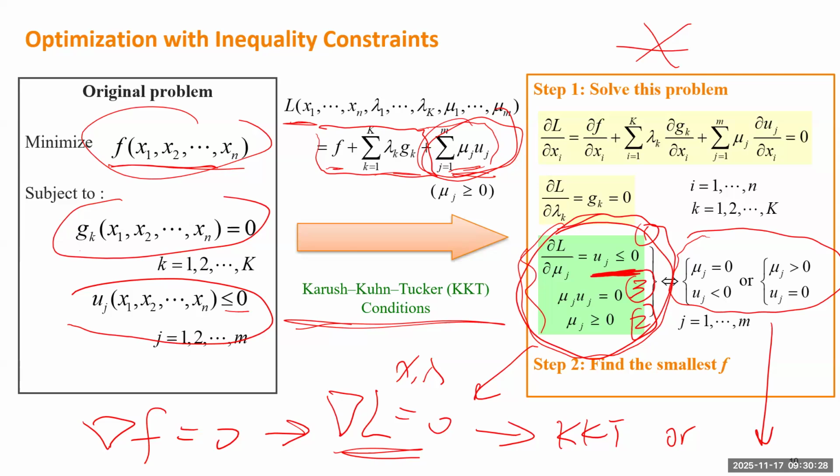Possibility means for each inequality constraint, it can be negative or 0. If you have multiple inequality constraints, let's say you have 100 generators, each generator's generation needs to be less than the limit or equal to the limit. So you figure out how many possibilities you have. You have unit number 1 reaching its limit but not the others, or numbers 1 and 2 reaching their limits but not the others. Together, that shows why there could be many possibilities.